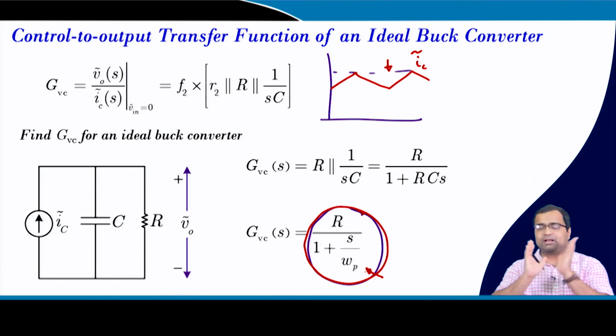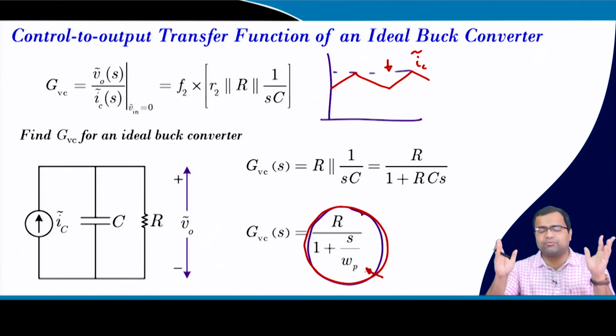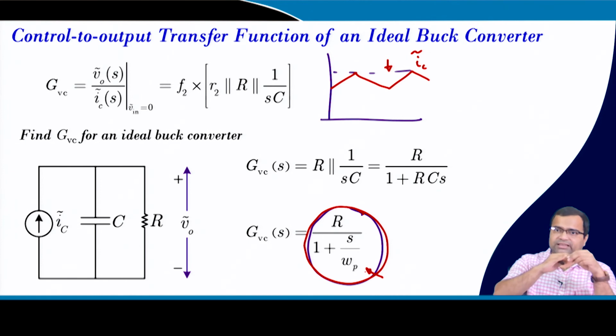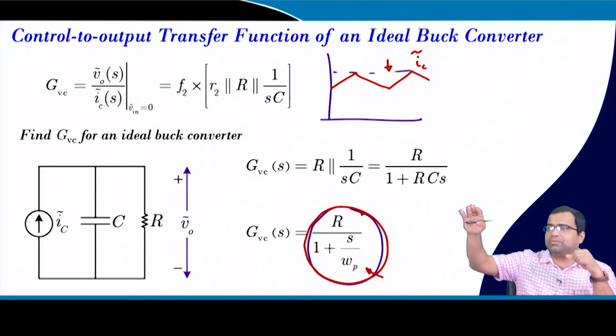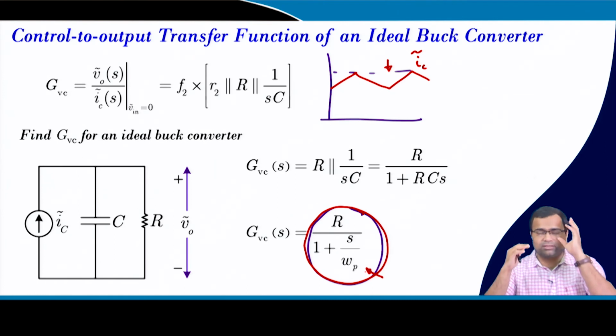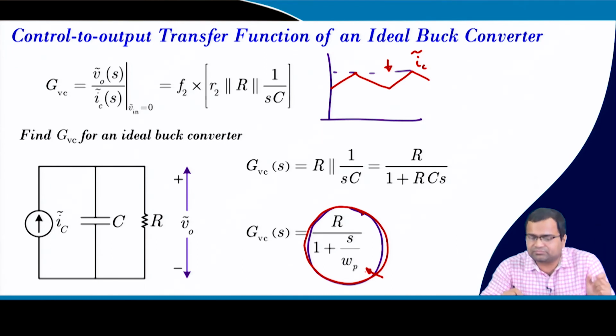Now, it becomes a first order system, and that is why we simulated the buck converter without load feed forward. If you go to lecture number 17, you will find the response after load transient becomes very sluggish, like an overdamped response, because it virtually behaves like a first order system, because you have made the current a control source. So, the inductor pole is as if you pushed it very far to the left hand side, that dynamics is not coming into the picture.